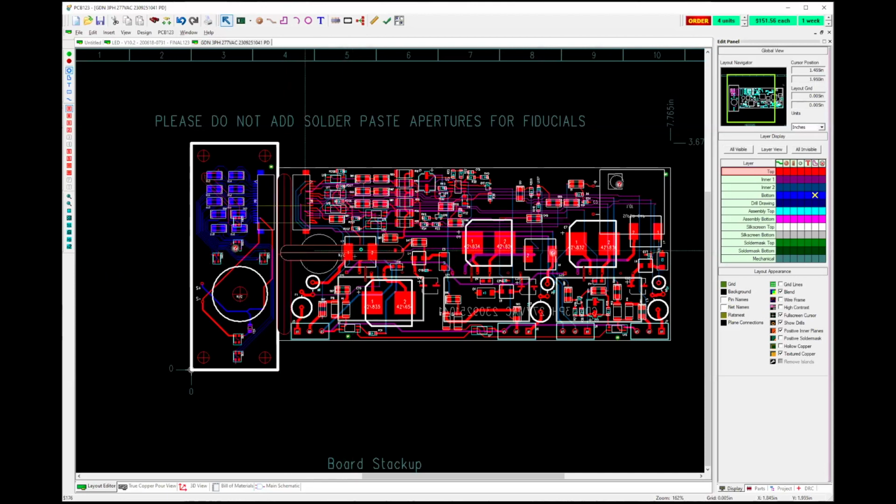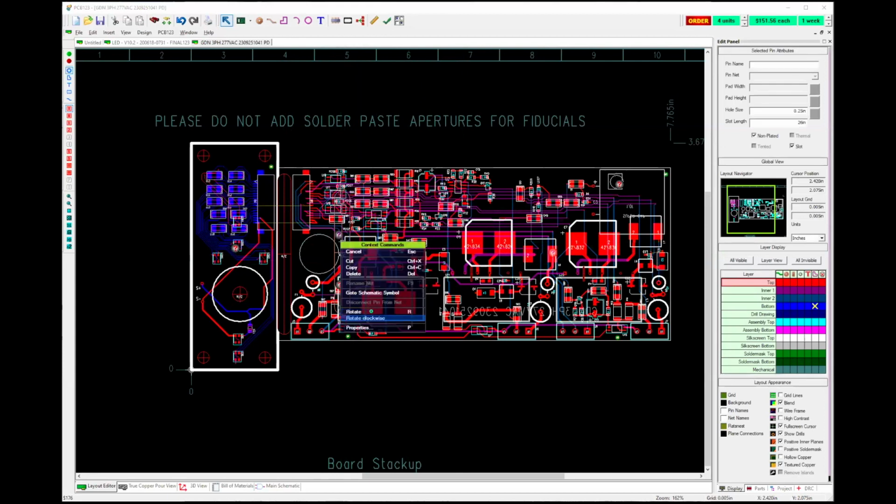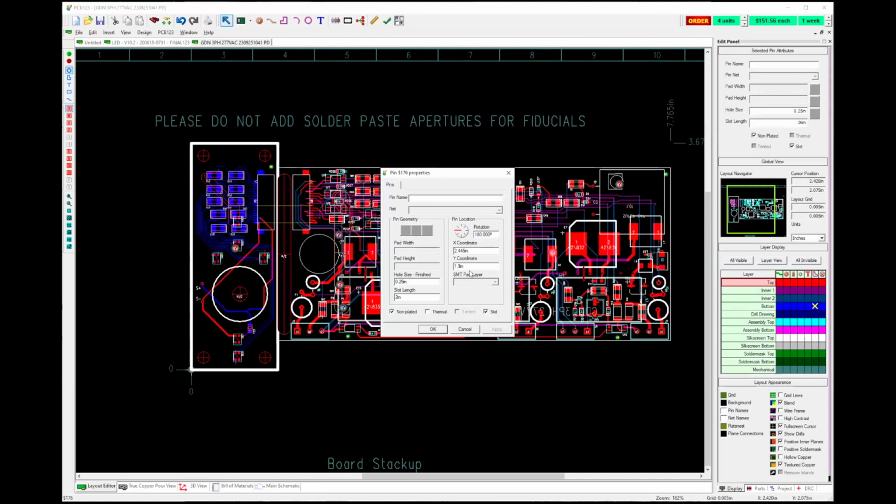And this will give you the ability to make a, you can make this a zigzag for creepage, high voltage protection, that sort of thing. You just put 2 or 3 in here. You can rotate it to whatever angle, give it a different angle if you want. Properties. You can tell it how to rotate here. And instead of 180 degrees, I'll say 25 degrees, and it'll put it in at 25 degrees.